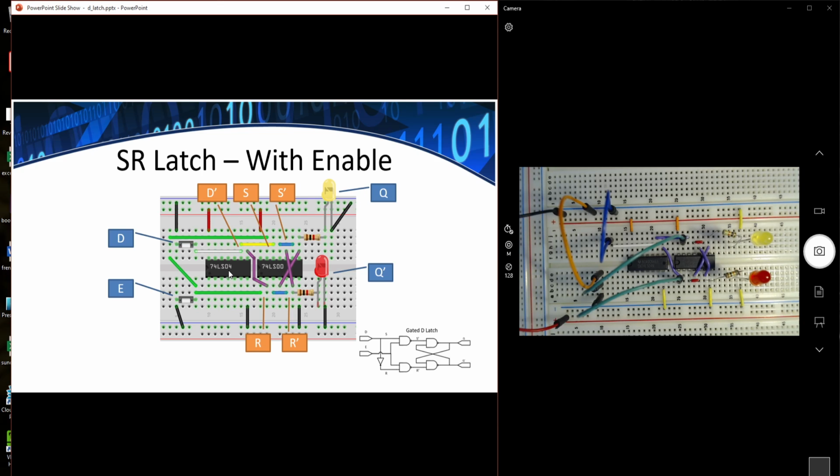We're now introducing a 74LS04, which is a hex, or 6, 1-input inverters. We can see where things are laid out. Each of these integrated circuits requires connection to the power rail on the VCC pins and ground rail on their ground pins.